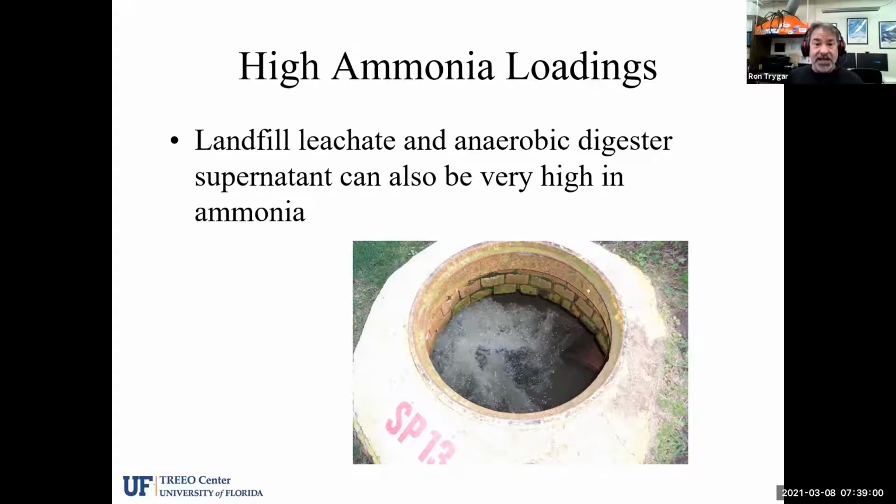So this leachate then has to be dealt with, and it could be done at the landfill, or we can actually try to treat it at our municipal wastewater treatment plants. And so we find that this leachate can be very high in ammonia and ammonium, and we want to handle that appropriately at the treatment plants ourselves. If we can bleed that into the plant slowly in a controlled environment, like pump it slowly into the treatment plant under our own conditions, when I say our own, as operators, when we can kind of control that instead of slug loading it, the treatment plant tends to handle it a little bit better.